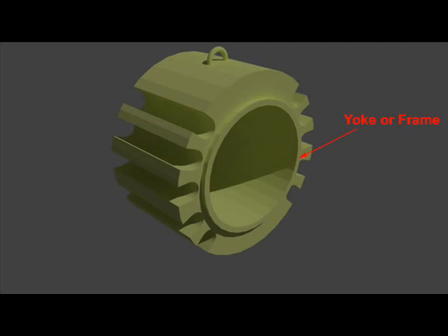Yoke is generally of cylindrical shape. The yoke acts as a cover frame of machine and carries the magnetic flux produced by the poles. Since the field is stationary, there is no need to use laminated yoke for normal machine. In small machines, cast iron yokes are used because of cheapness, but yoke of a large machine is made of fabricated steel due to its high permeability.